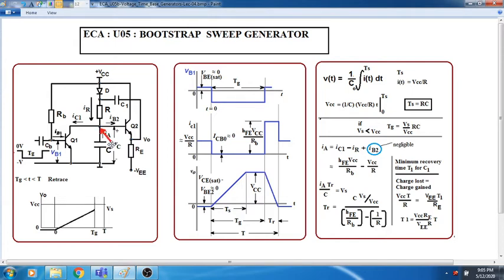less than Vcc. Once the gate pulse is over, you can see here, the base voltage of the transistor Q1 will again become positive, and this will force the transistor Q1 to go into saturation. So whatever is the final voltage here, the capacitor must now start discharging in the opposite direction. Whatever charge is accumulated here will start discharging as soon as the gate pulse ends. That means the voltage across the capacitor at Tg has to start falling down. Okay, so this point you remember.